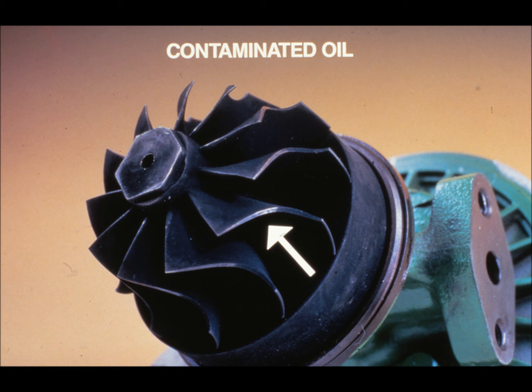Contaminated lubricating oil can also cause a failure. Abrasive particles in the oil will cause excessive wear within the turbocharger, resulting in the wheels contacting the housing. Contamination can result from defective or plugged oil filters, improper oil change intervals, or a debris-generating engine failure.